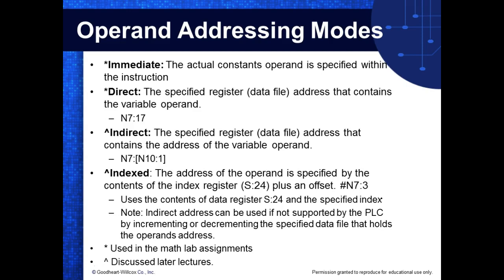We do that all the time, where we can build tables inside our PLC, like tolerances and stuff like that. Then the PLC automatically pulls from that table, and it might do that 5 or 10 times. But if I need to change those tolerances, I don't have to go find all those instructions, I just go in and do what? Change the contents of the table.